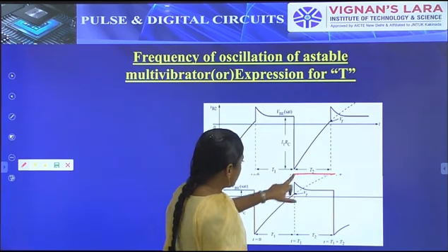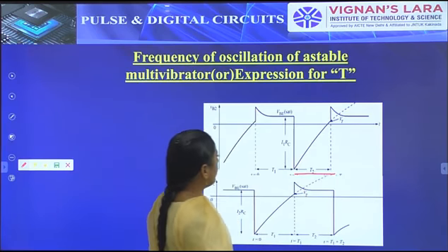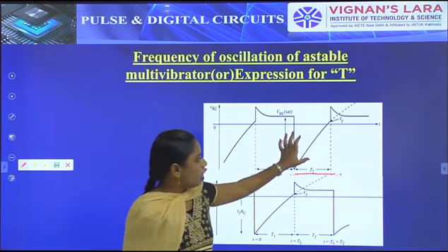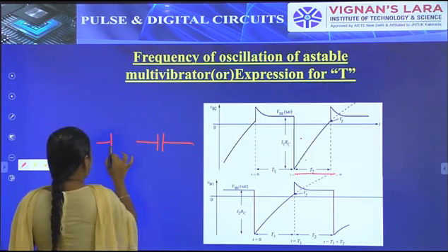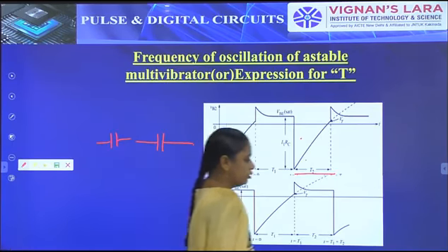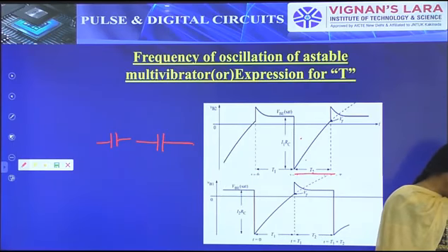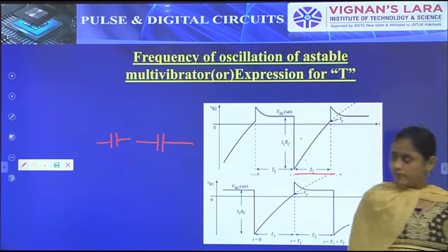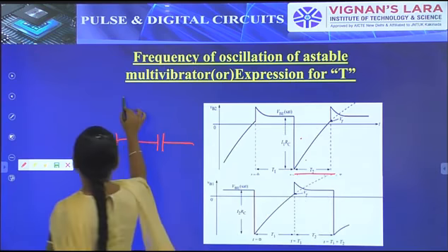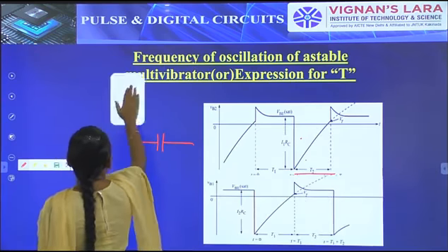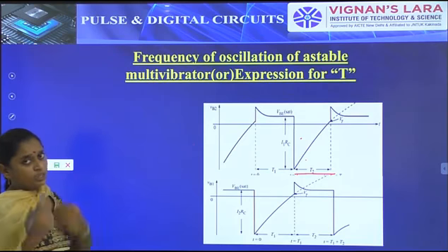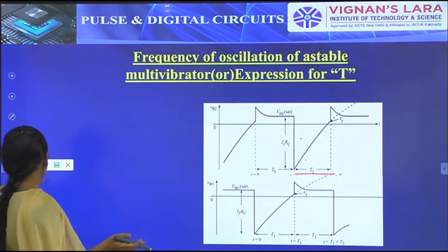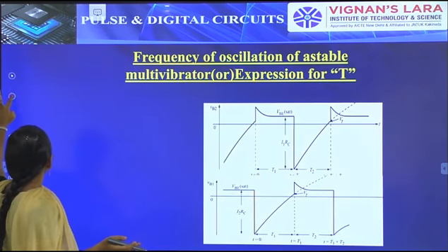in this particular time C2 starts discharging. Then the node B voltage, in this particular interval of time, for C2, sorry, C1. So in this diagram we have to replace like this. In this particular interval of time, C1 starts discharging and this resistor will be the R1 resistor. At this particular interval of time, we have to check the condition like this. So the VB voltage increases gradually. Then what happens, from this diagram we have to check the condition.